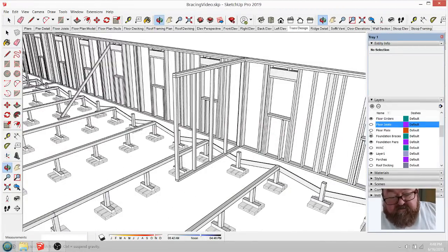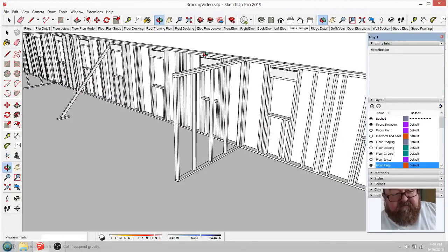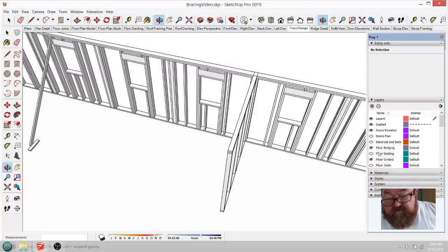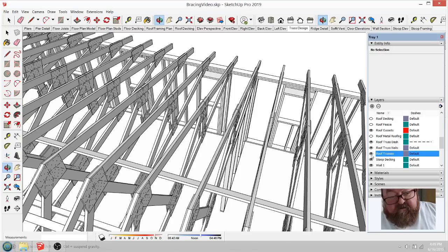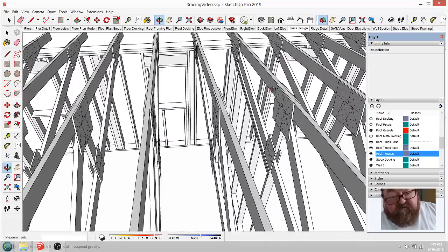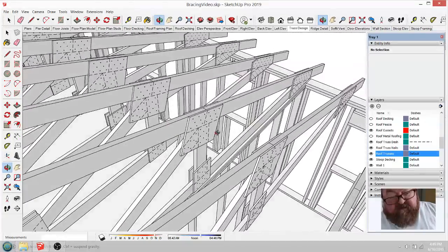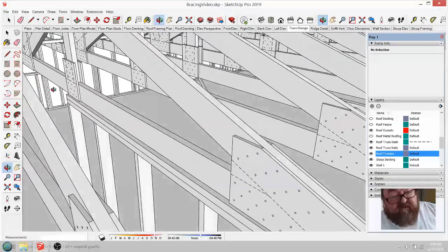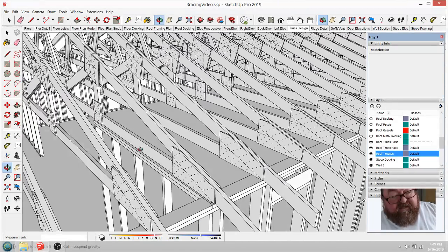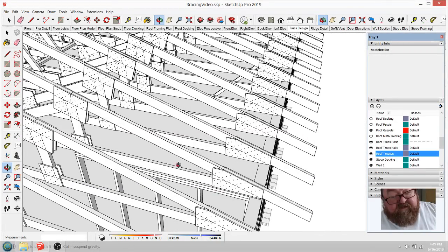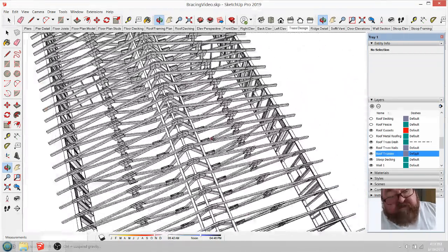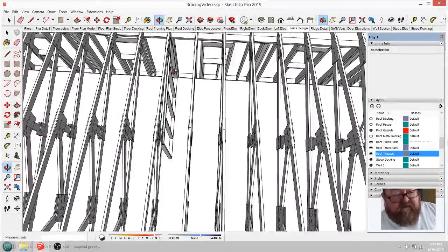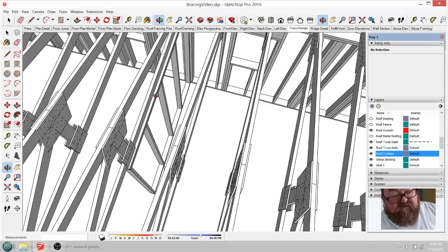And you're also going to be fastening it to the roof trusses, which I know I'm not going to have blocking right now, but I'm just going to show you. Okay, that one, well, we got lucky, right? We can fasten this wall to this truss, we can mechanically fasten that, that's actually a perfect situation there. But let's see how our other one worked out. Well, I can't believe they both worked out under trusses.